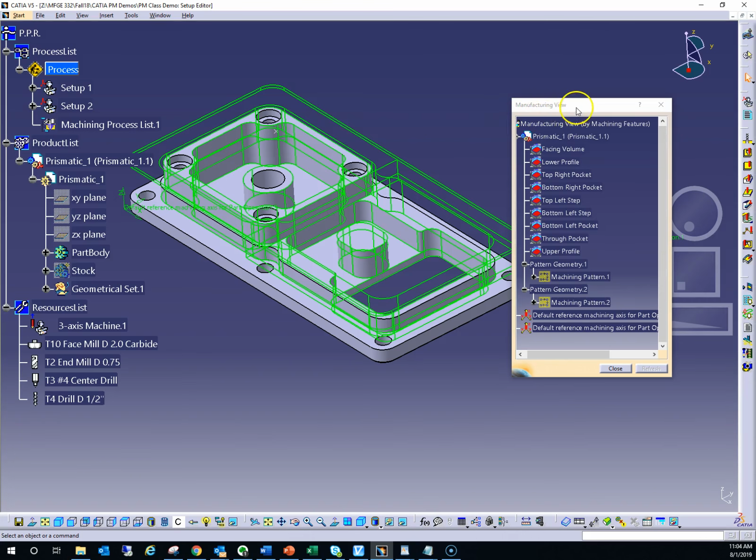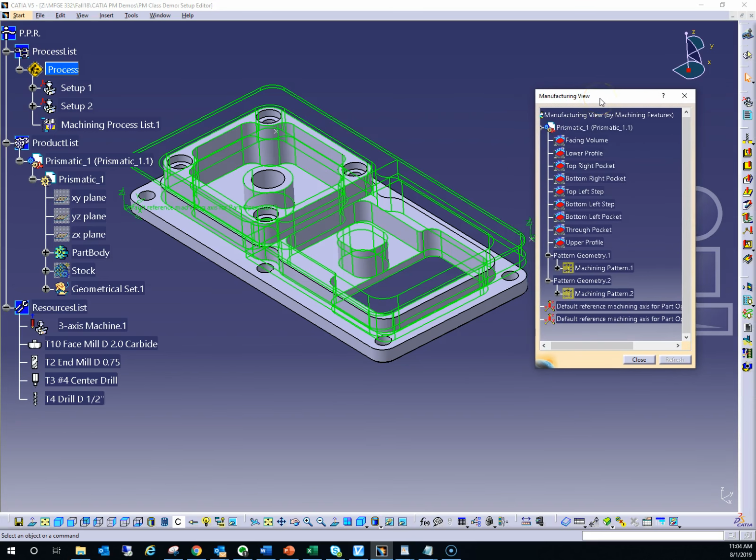of the part and how those play into setting up your various roughing components of your operation and the finishing component. So again, this is a brief overview, a brief summary of process planning, as we call it, machining process planning. And this is one part of it, because of course there are things like the actual speeds, the specific tools you pick, and so on, the machining strategies for each volume that you have to also decide upon. But this step here, where you figure out how to decompose the stock and come up with a strategy for how to remove it with operations, is a very important first step.